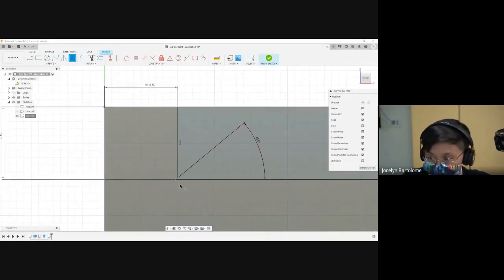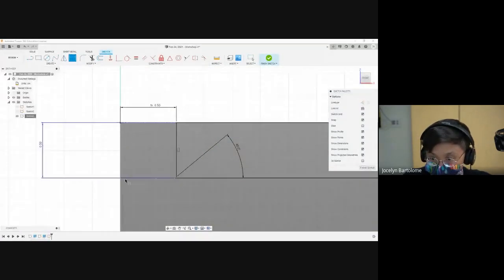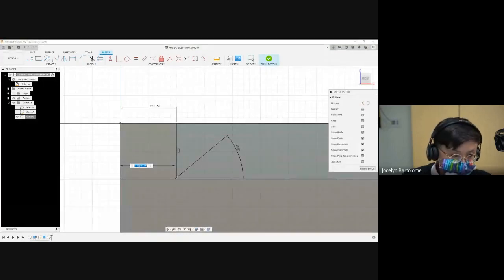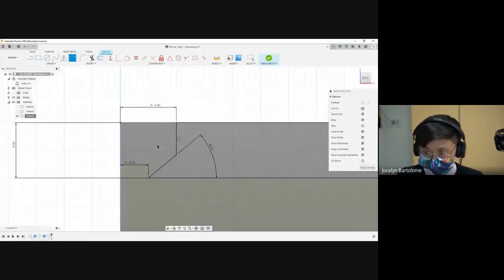From there, I'm going to do the exact same thing with this bottom point and the outer edge. So I'm still using the dimension tool. Click the bottom point, the outer edge, once more. And instead of entering just the number, we can just do D8 divided by 2. Or you can simply use whatever letter combination Fusion gave you earlier. So as you can see, everything just fixed itself, and this is where we are at right now.